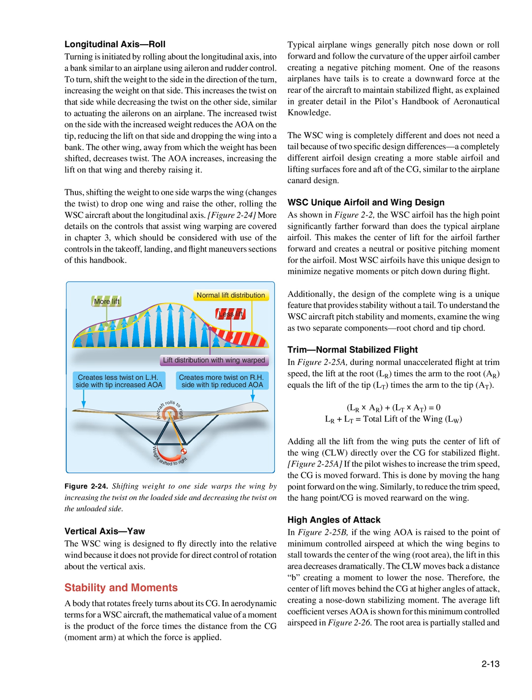High angles of attack, Figure 2.25B. If the wing AOA is raised to the point of minimum controlled airspeed at which the wing begins to stall towards the center of the wing, root area, the lift in this area decreases dramatically.